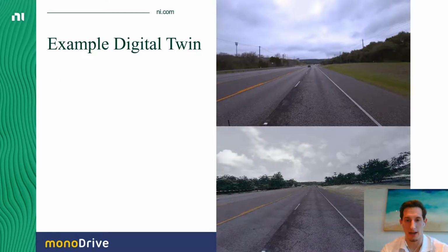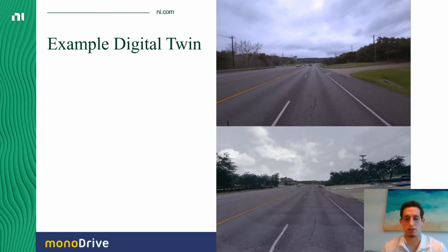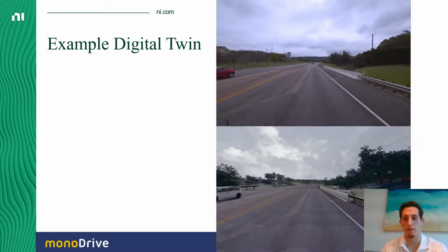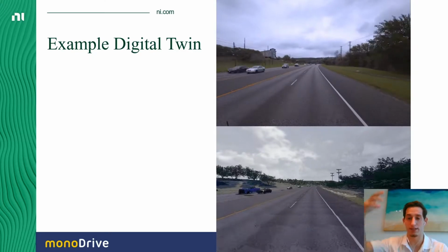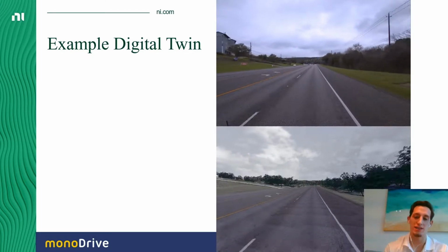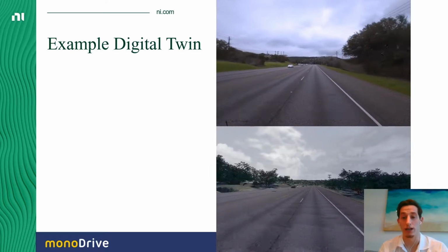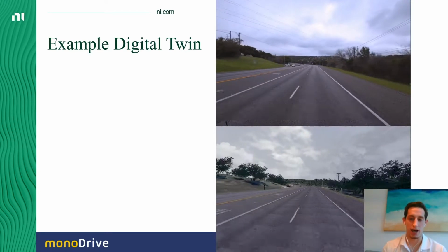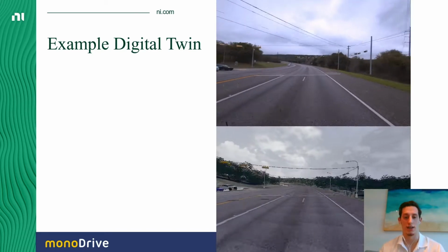One thing additionally I'll add is that some unique capabilities of simulation that some simulation companies provide is the ability to create digital twins or real-to-virtual environments from a pre-recorded drive into a synthetic world. So that means that if you encountered a specific scenario in the real world, then you can recreate that digitally in a synthetic world. And that lets you iterate on those encounters you had in the real world. Hey, I almost had a crash. Let me see what my vehicle would have done if it was raining instead. So you get the opportunity to do that.